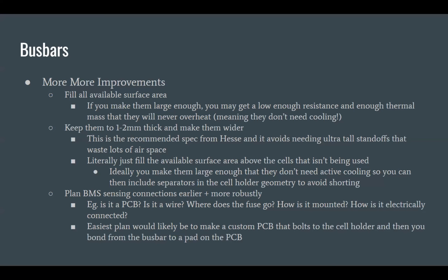I'm a little bit confused about something. So the BMS needs to somehow have wires connecting it to the voltage sensors and the battery. And you can either use a bunch of little wires that you have to connect somehow, or you can make a circuit board. And the circuit board is a bunch of little wires on a sheet of fiber. And so it's just an easier deal. You still need to attach that circuit board. Right, but the circuit board has pads where you want to attach it and then where to bond it. Yeah. And it lets us solder the fuses on instead of having to figure out some way of mounting the fuse to a piece of floppy nickel, and it's like this is just easier.